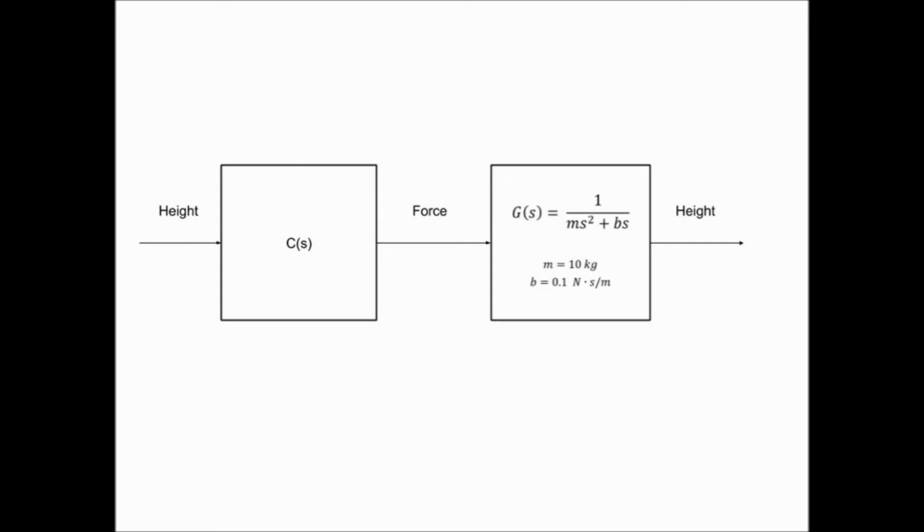We determined that our plant was very likely to be disturbed by an outside source. We selected wind for our main disturbance, as this makes the most sense for a quadcopter. Wind can be modeled as a unit step, unit impulse, or unit ramp. To make our project interesting and the most robust, we selected unit ramp.